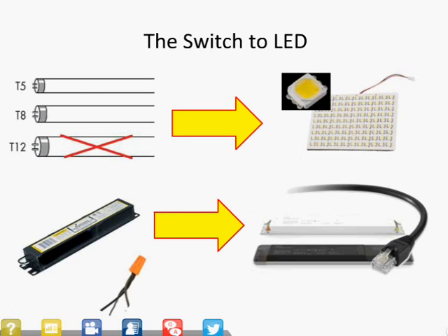And you've seen these. These are the large fluorescent tubes that you've seen in many spaces, including in lots and lots of data centers. New LEDs deliver better light and are virtually maintenance-free, as we said before. Then there's the change to the ballast. Fluorescent fixtures have a ballast in them, shown on the left here, and that is wired via traditional wiring with wire nuts, as you see there. New LED fixtures, although most of them are still AC powered, have LED drivers in them that do AC-DC conversion, but the control system is interfaced via a Cat5e and a Cat6 cable. So it's simple plug and play, and it really gets into the realm of datacom contractors and data center people.